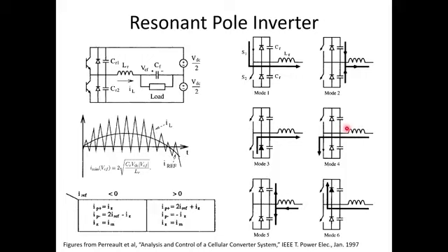That negative minimum current is actually a function of the voltage. Okay? So if I just didn't have enough current, this voltage would ring up, but it wouldn't ring up all the way, and then it'd die and I wouldn't get there, right? So I have to have a certain positive current to make sure I can ring down, and a certain negative current to make sure I can ring up.